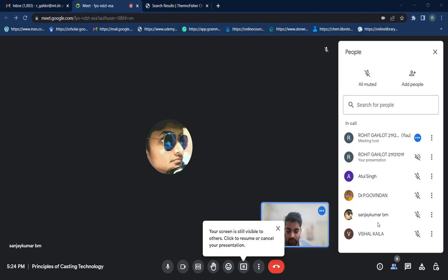For die casting, I have summarized it in points: it provides complex shapes within close tolerance. Second point, these are produced at a high rate of production. No machining is required, in brackets. Third point is these are much stronger than plastic injection molding, produced with thinner walls. These are durable and dimensionally stable parts. It can produce thousands of identical castings within specific tolerance.